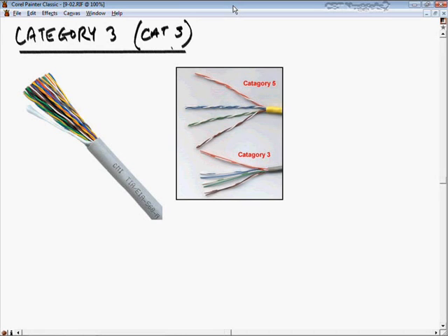The wire is typically 22 to 26 gauge, with more than one pair being carried in a single jacket or a sheath. So you can see here we've got the yellow sheath here and a gray sheath here. Now, because wire carrying electricity transmits and receives electromagnetic energy, nearby pairs of other wires carrying signals can also interfere with them. So this is called crosstalk. To reduce crosstalk and other sources of electromagnetic interference, EMI, we twist these wires.